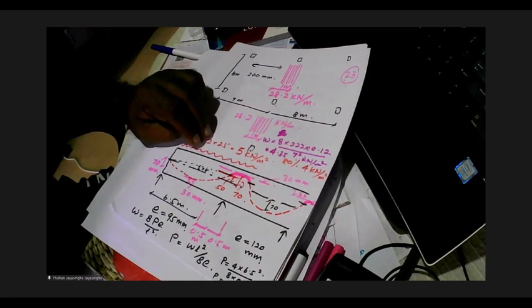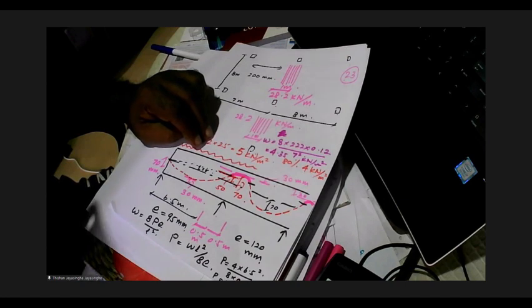And based on axial, then we also know the amount of loads that are applied due to live loads. And for that case, we can get a bending moment diagram by analyzing a one-way slab, one-way beam, we can just analyze a beam by using SAP 2000, get the bending moment diagram. From that, you know the bending moments in the span, and check for the span moments, the stresses. And if the stresses are satisfactory, then you don't have to worry.